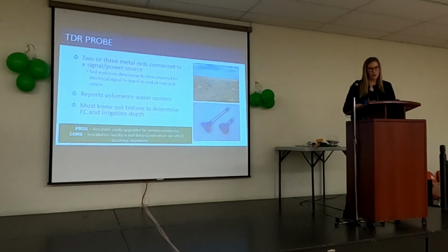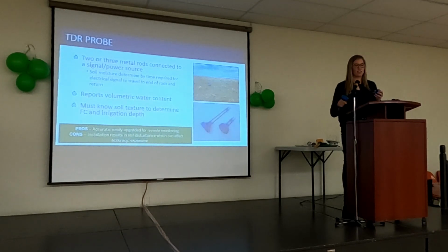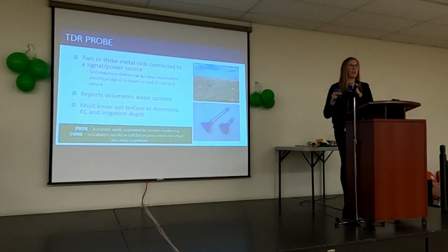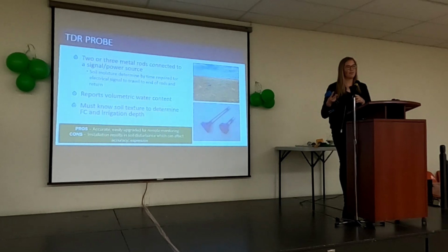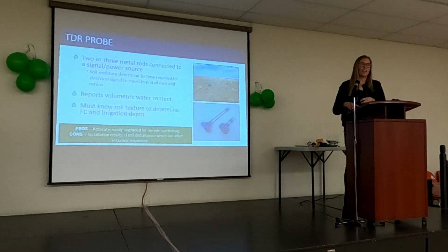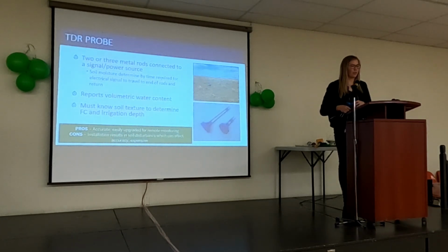And there's a few cons, I guess, also with the installation. These really require tight contact between the surrounding soil and the probe. So if you put these in without that good contact, it will give inaccurate readings. So not necessarily a con unless your probe is installed improperly.